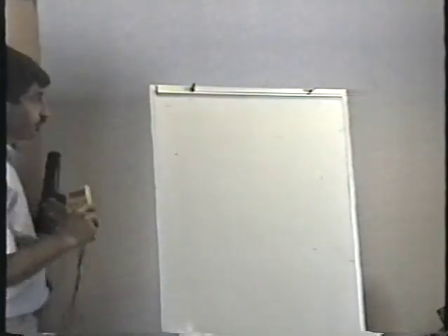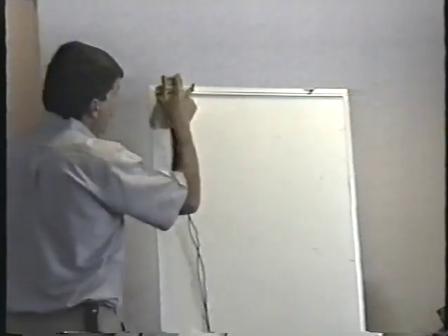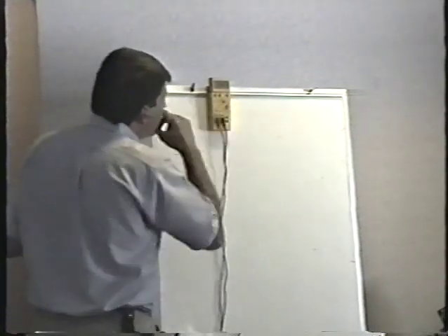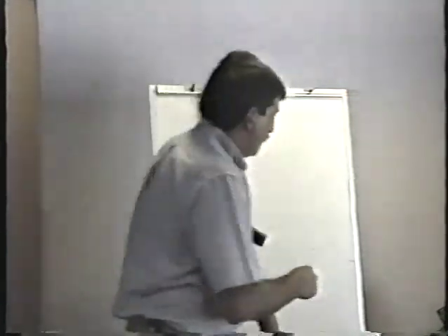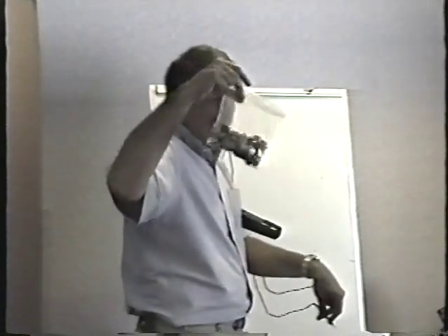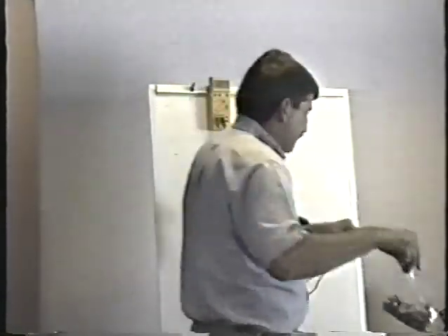And if you look at the chart on the top of page 10, this tells you how the transistor test works. And again, you're using the diode test setting of your meter. Here's how this works. Don't do it now, just watch me. You're going to have a chance to do 40 transistors in just a few minutes, okay? Because I got this big bag of transistors here. You're going to check every one of these. Half of them are good, half of them are bad, and you'll see how this works.